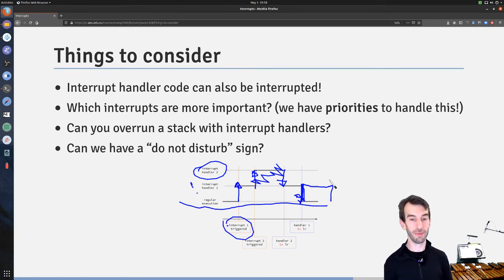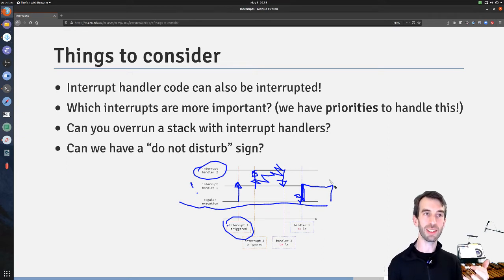And for this reason, because interrupts are unexpected, they're messing up our expectations as to being able to predict precisely what is going to happen in a computer in the future. So if we're trying to verify that a stack will never be overrun, then this could be a problem for us. In practice, this is not something which tends to happen too much in normal situations, unless the system has a kind of poorly designed piece of software running on it.